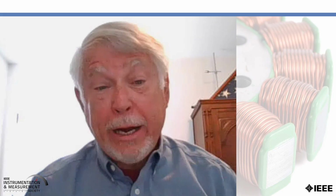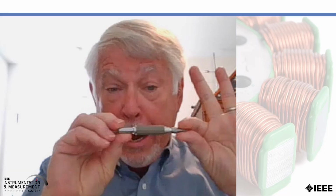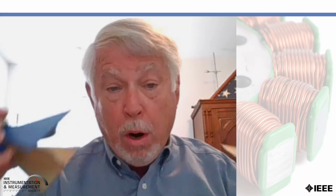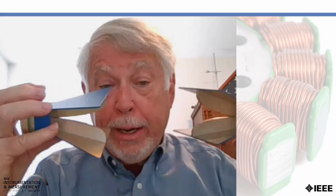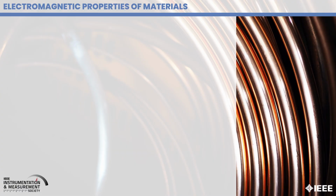This presentation deals with measuring the electromagnetic properties of materials using transmission line techniques. The transmission line could be an air line, section of waveguide, or two antennas pointed at each other with the sample placed between the two. The electromagnetic properties are permeability, permittivity, and conductivity.